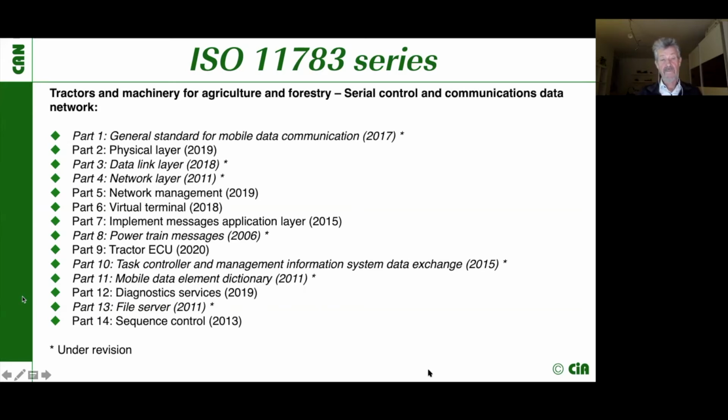interoperability issues. Interoperability is still a huge issue when it comes to different versions, because if there are different versions of the Isobus implemented which do not fit together, then the farmer has a problem that he has to know which version is implemented in the tractor and which version is implemented in the implement. But there's a database provided so that you can easily see which devices can interoperate with which other devices.